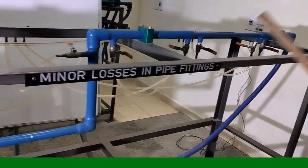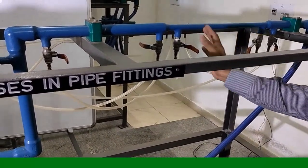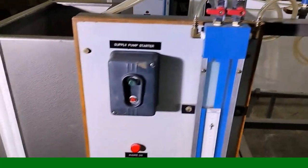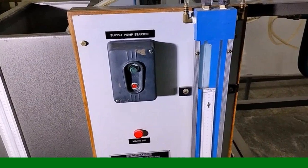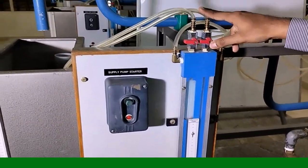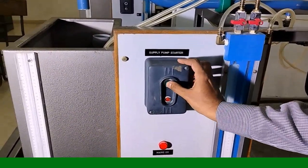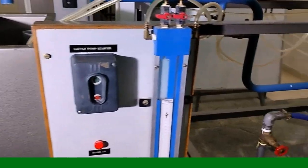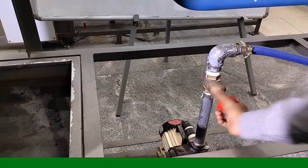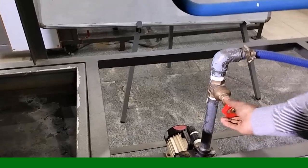Almost the settings are over. Now I am going to switch on the pump. Later, using the control valve, I will give some discharge. First, for the first reading, I will remove the water bubbles. Later, I will take the reading for only one trial. The pump is closed. I give some discharge. Now I am going to remove the water bubbles for the first reading only.